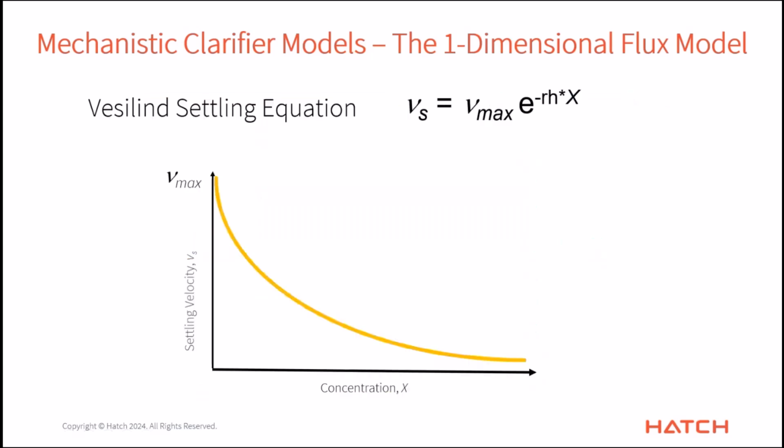Right. So the settling equation itself is actually a bit of a challenging thing. It's got a lot of moving parts to it here. But it is the thing that controls the quality of the settleability of the sludge. So there was previously a very simple curve here that was the early days of settling models.